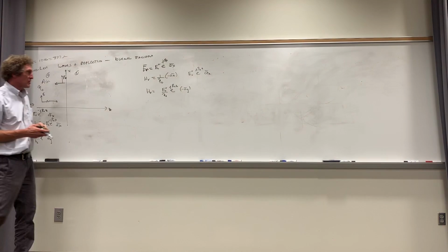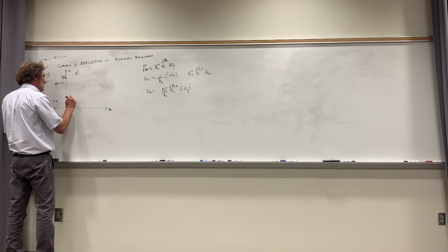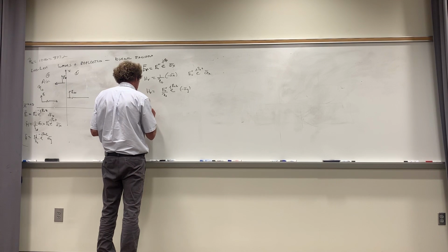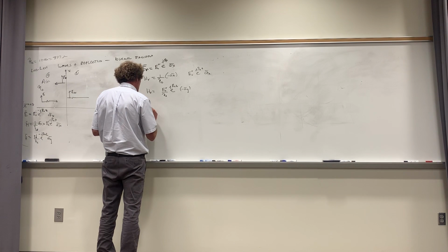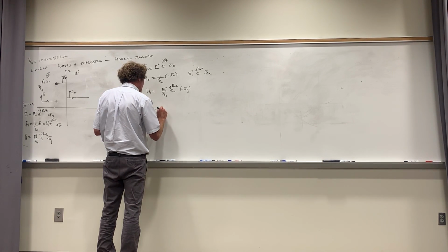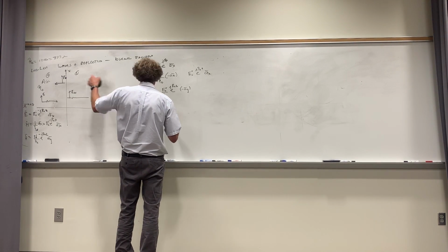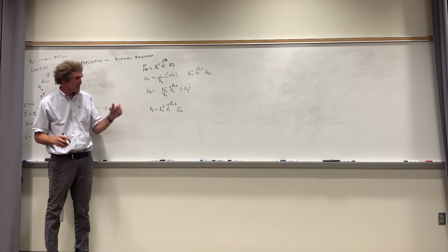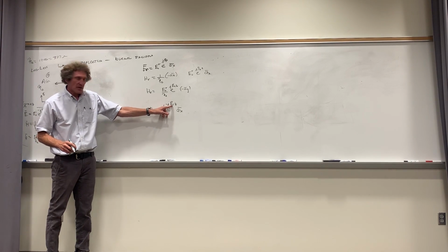Now something else that happens, you also have a transmitted wave. You're going to have a wave here that transmits. And the E field will be in the X direction, so you're going to have some E transmitted, and that's going to be some E not transmitted, e to the minus j, and here it's beta 1, because that's region 1, times z, and it would be in the AX direction. Now, it's the same as the incident field, except for one fact. Now it's got a different value of beta.